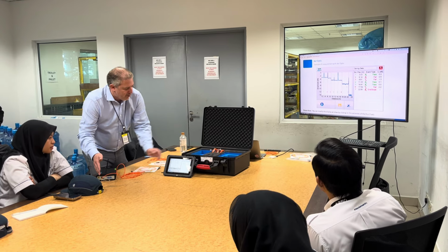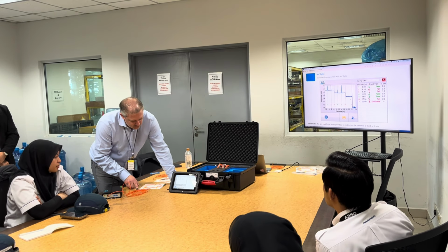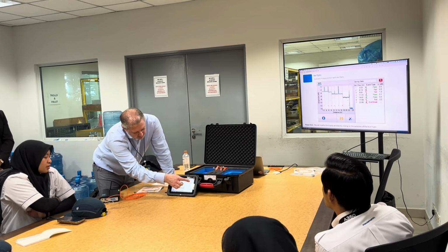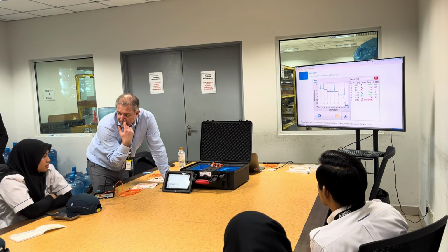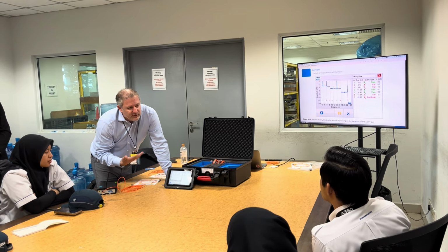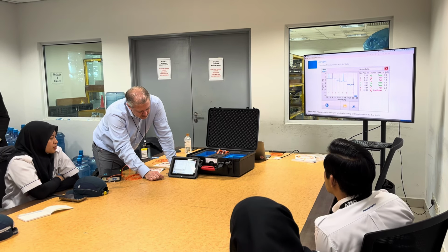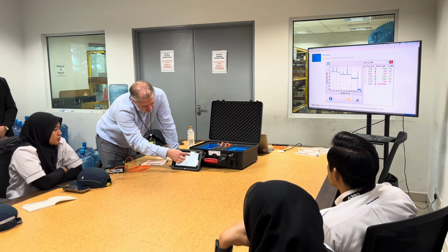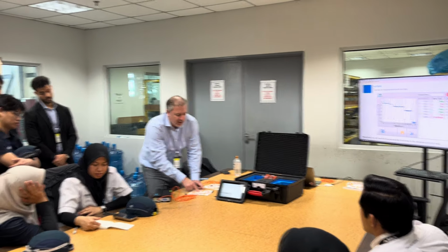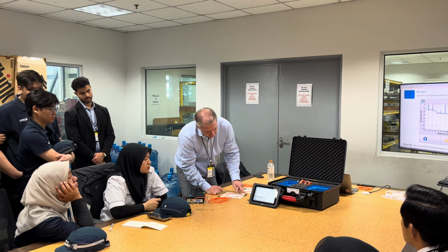So the launch fibers are always the same size. Okay. So 0 is always this point. You see, in that case, I have a 0.3 insertion loss. Since my criteria was 0.2, it says failed. Actually, 0.3 is still very good, and we can play after to simulate some damages. Then I have the second connector about 3 meters after. So I told you I have a 3 meter fiber, and I have this connector now, which is 0.1.